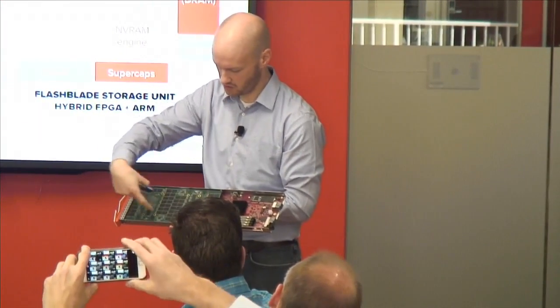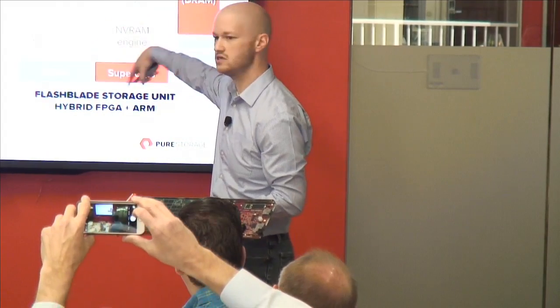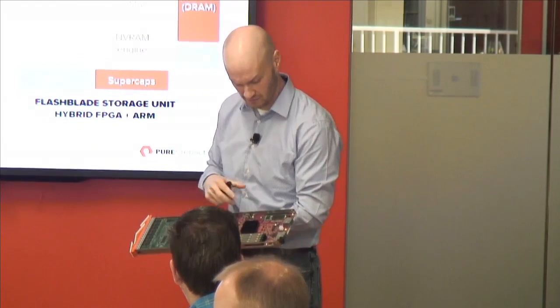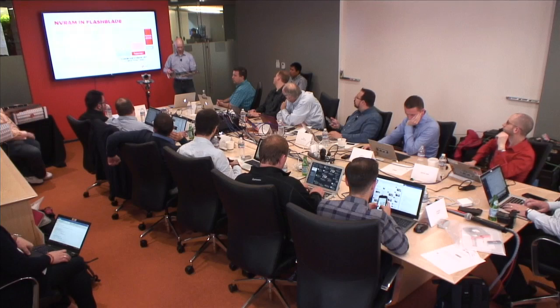So great question, and I've got a picture on this coming up, but I'll just show and tell here since you asked. So this is the 52 terabyte blade. The green boards here are the flash. There are actually 3 of these storage modules. Even though it's gone to a planar card, it's still logically a modular unit the way we started. And then this red board in the back here is the computer. It's an Intel CPU, DRAM, and then the connections into that switch fabric are done through a mid-plane. And so the overall enclosure, the entire chassis, is a modular chassis. This is a field replaceable unit. In production, there's a cover on the top.